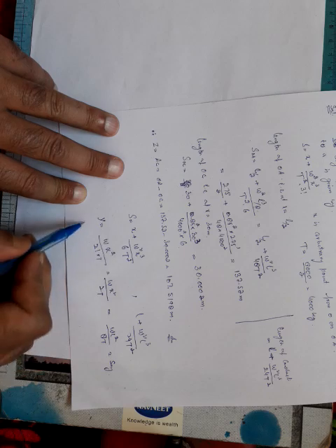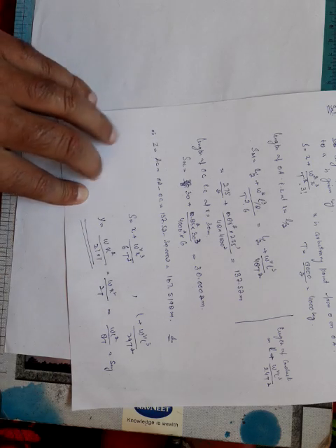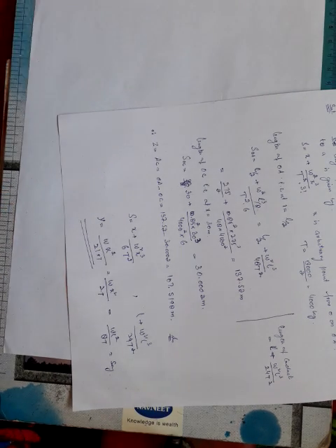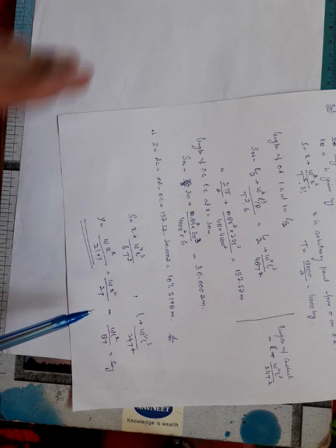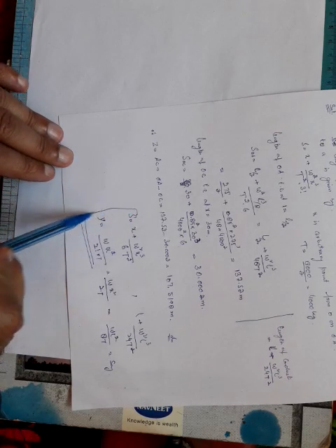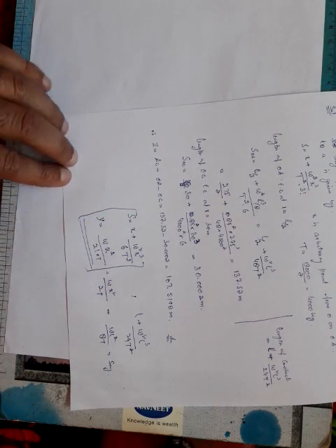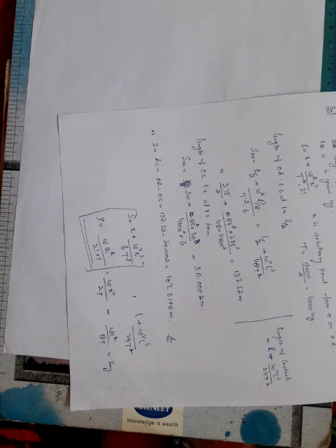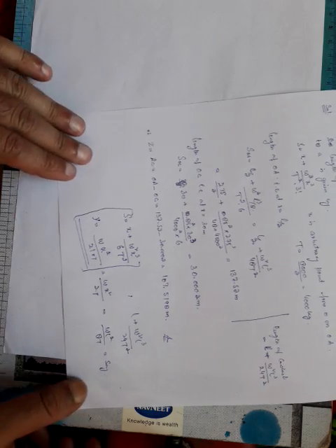So you generally should remember this formula, then you can calculate any vertical distance. This vertical distance is the maximum sag W L square by 8T. But in general, if you have to calculate any other vertical distance, what I mean to say is that in general you have to just remember these two formulas for calculating length of the conductor or sag.